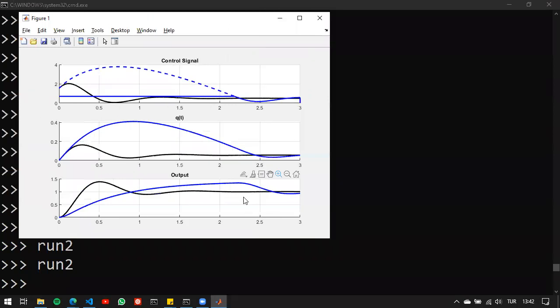Now, in order to solve this problem, there are two most used ways. There are maybe multiple ways. And one of them is to just disable the integrator during saturation. So you can detect if you're saturated, if you're above or below the limit. Therefore, what you can do is just turn off the integrator.